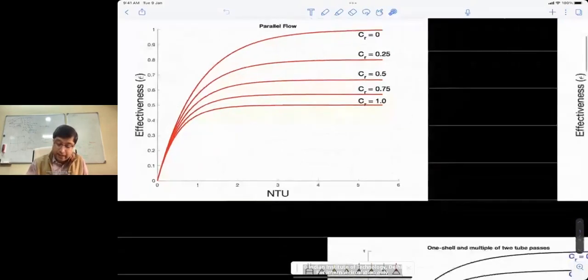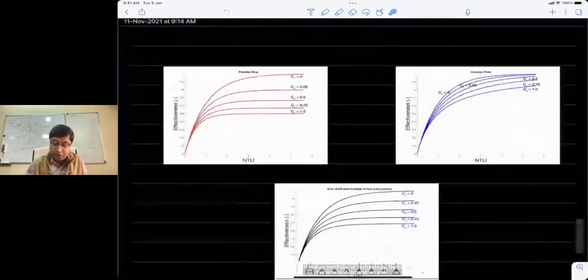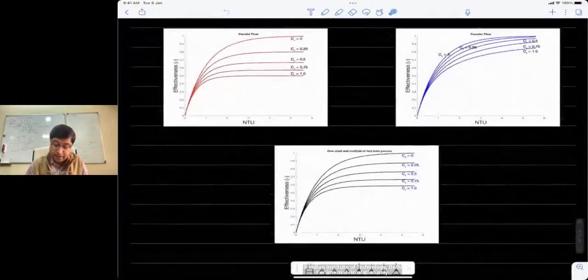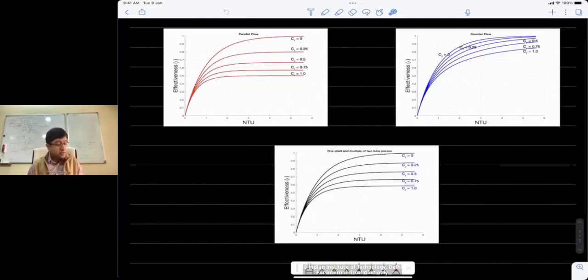The other thing is that if you compare the three heat exchangers that have the three effectiveness relationships that I've shown here, it is also easy to see, or at least I hope that you can make out from the pictures that I also put up in the last lecture notes, that for the same NTU, the counterflow heat exchanger gives the highest effectiveness. Okay, so that is quite understood, that counterflow works best. After counterflow is actually, which I have not shown here, the cross flow heat exchanger in which the two fluids are unmixed. That sketch is available in the book. You can go and check.